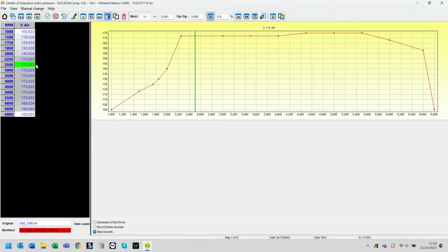Now, without seeing this at the side, the temptation might have been to do sort of a diesel tune almost. We'd start at 1500 RPM, bring that boost in as soon as we can, and carry it on all the way through to our sort of peak torque. The problem is here, if you look at the standard build-up, it's quite smooth and progressive, has a spike up at 2200 RPM, and then no sort of linear dome or curve to it, it just cuts the boost. This is where understanding the vehicle you're tuning is so important when it comes to modifying any ECU.